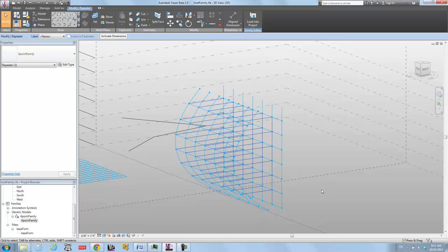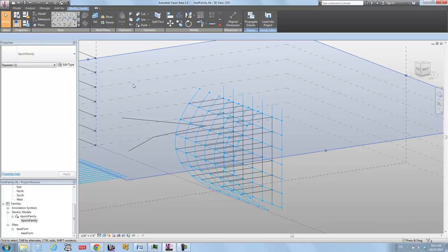That's just relying on a lot of the ability to add dimensions and add rationale to it that we had covered earlier. Did you make the levels equal to each other, which affected the intersection? Yeah. So the parent-child relationship right now is getting a little bit more intense. You have a divided surface over here, and you have a divided surface over here. The thing that they have in common is these levels.